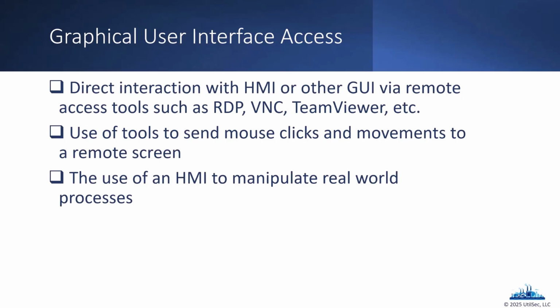But remember, the HMI is there to give the operators visibility into the process that's happening in the real world, and then to be able to make changes. So think, if an attacker gets into the environment, how exposed is that HMI? How exposed is the process? Or what happens if you do expose the HMI to the internet? Remember, you're not only exposing the HMI, you're exposing the process, and you're exposing control over the process to where an attacker or pen tester can have an impact.